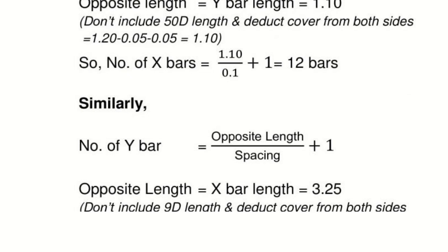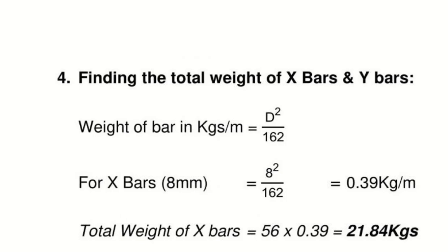If you go into the examples which we did, you will see we were also taking different values for the cover for different items, because for beams it's normally 25 millimeters. If you want you can take it the same, but read the specifications, maybe it's written there. One of the sections, maybe it's already mentioned. If it's not written, you come and ask Mahdi, right? Yes, you take his number.